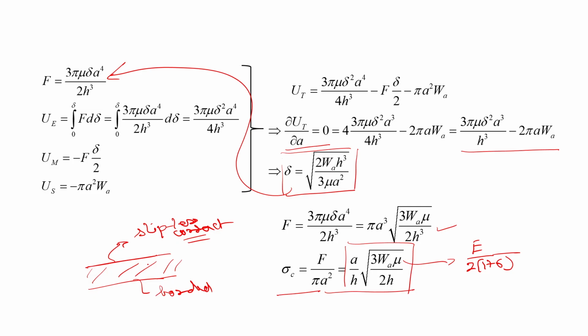So now let us say instead of slipless, if you have perfect slippage, then the boundary condition changes. We know that for perfect slippage, what will be the boundary condition? The boundary condition is that the shear stress there is equal to 0. So that means that sigma_zx is equal to 0 at z equal to H. So you apply this boundary condition. We have done similar problems in the context of the rectangular geometry, and we can do the similar approach over here, too, and we can obtain the required expressions. So I am leaving that part to you to derive on your own.